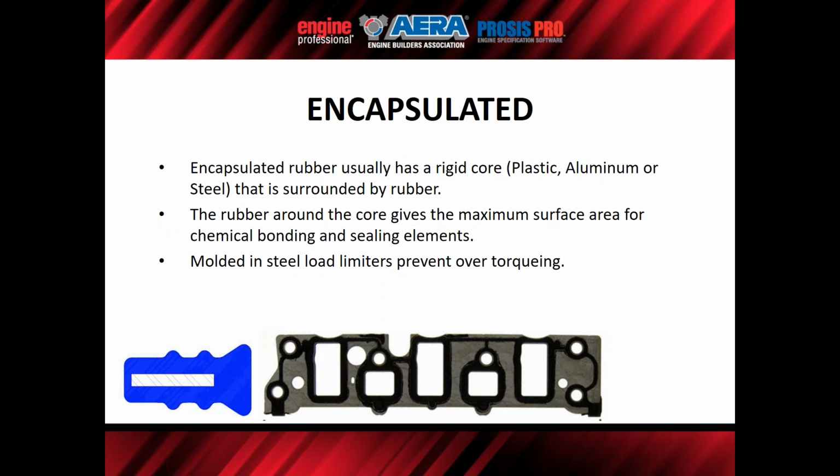These particular designs usually include extra beads. The extra beads provide insurance for pitting. A lot of these engines back in this time frame had what they call electrolysis issues, which was like a poor ground combined with a bimetal condition with the extended life coolants. You get all those together, and poor maintenance from the end user, not taking care of their cooling system, and you get this electrolysis, this chemical attack that would go after the weak link in the joint, and that is usually like the aluminum